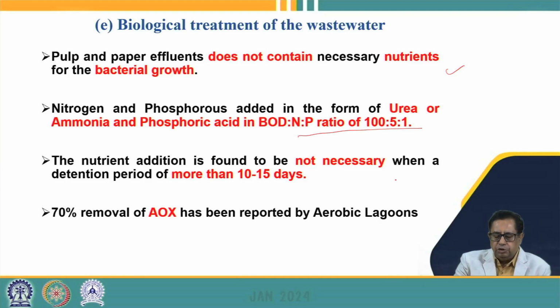It is also possible that nutrient addition may not be required if we are providing a larger retention time. For example, if we are providing more than 10 to 15 days of retention time, then nutrient addition may not be required. Similarly, we can also find that in the aerobic lagoon, nearly 70% removal of adsorbable organic halides can happen by the aerobic lagoon treatment.